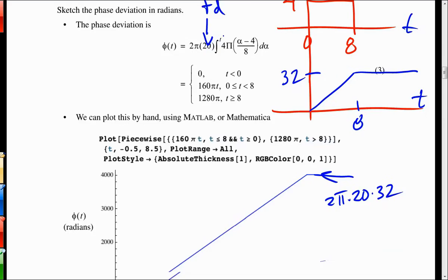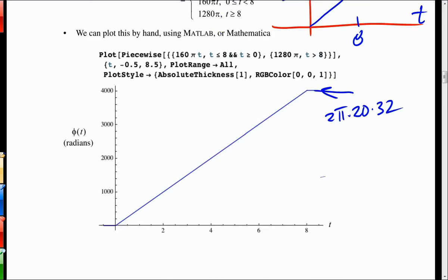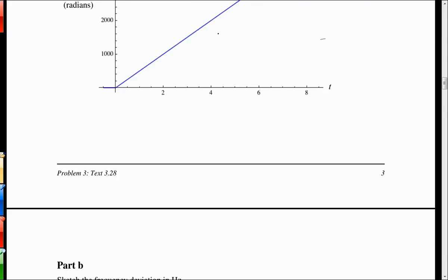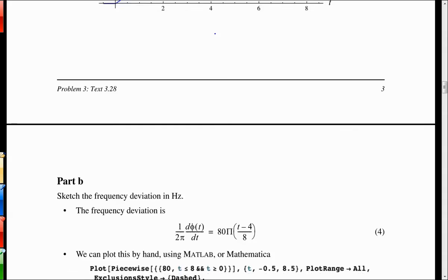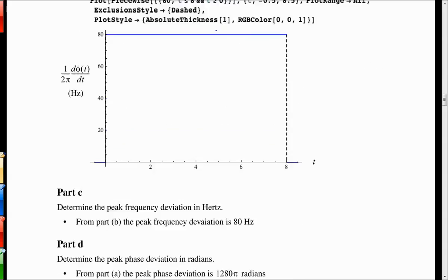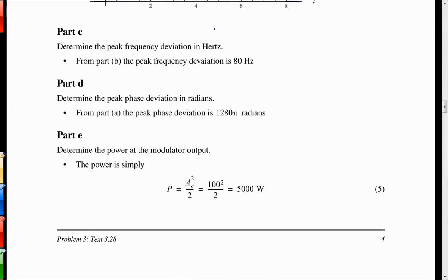You can't plot a Bessel function spectrum for this. This is actually a pulse type FM, so it's a little bit more complicated spectrum, but you can get the peak frequency deviation, which is 80 hertz peak deviation. So that could be one. That could be a calculation.